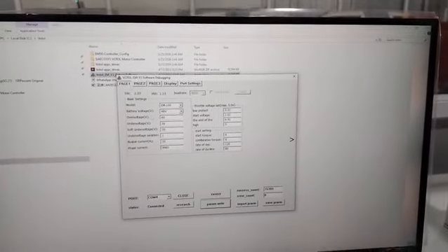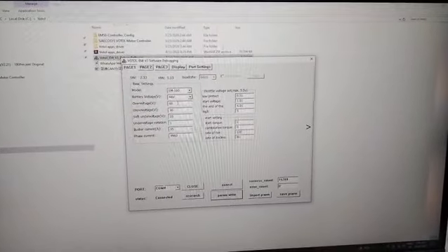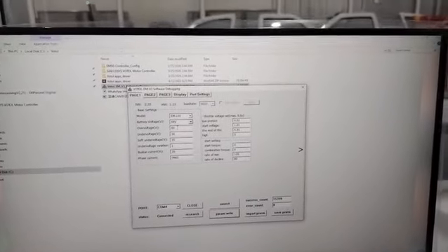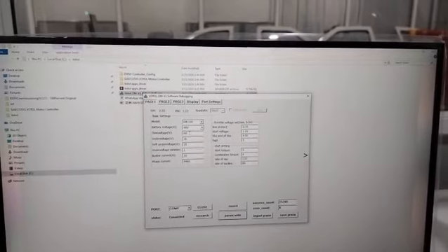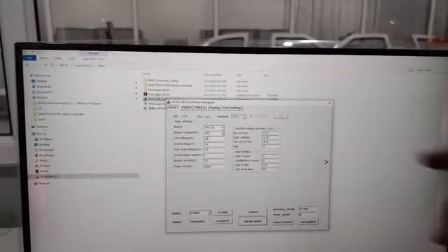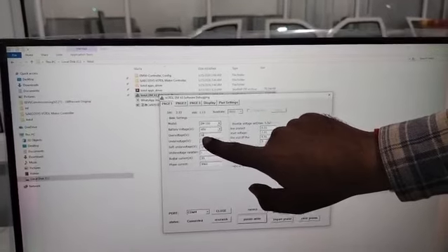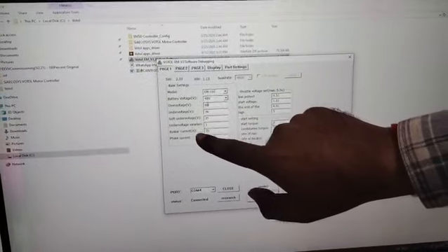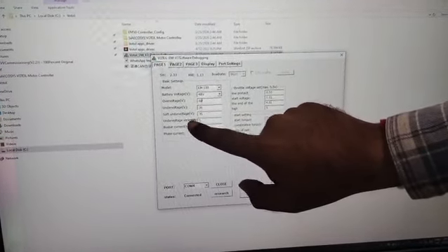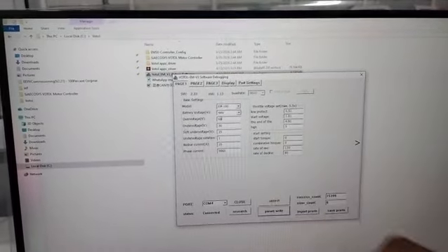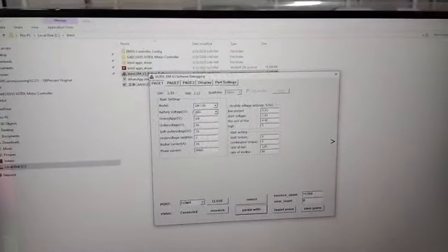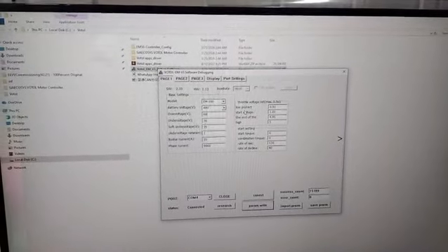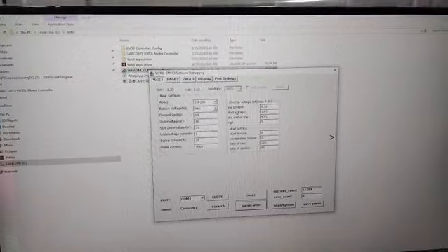We check here the under voltage and over voltage fault, which is automatically organized. Basically we have manually organized this. So this is the under voltage and over voltage fault. Here is the bus bar current. Here is the voltage variation for the under voltage and over voltage fault, and here is the phase current. So these are the basic factors we have to tune in a hub motor.